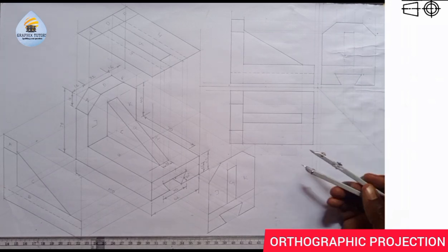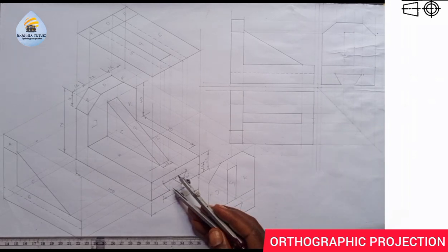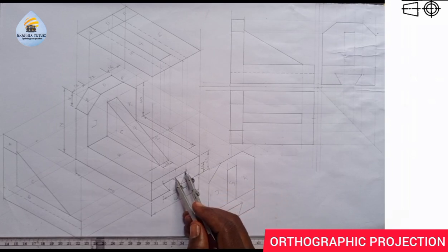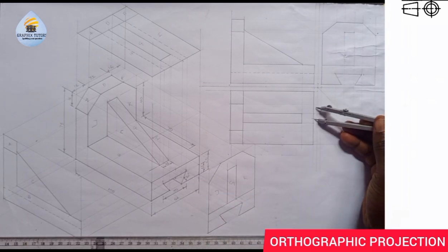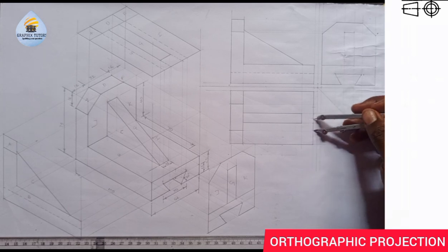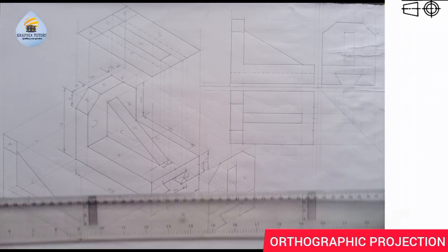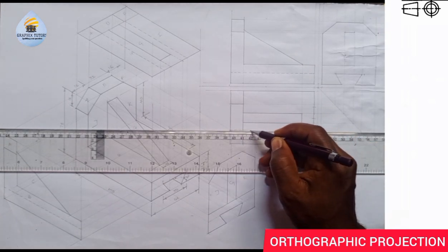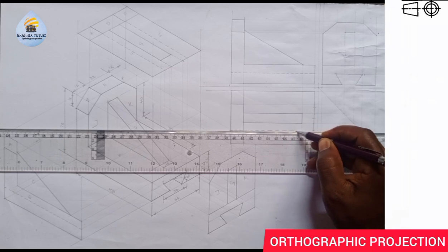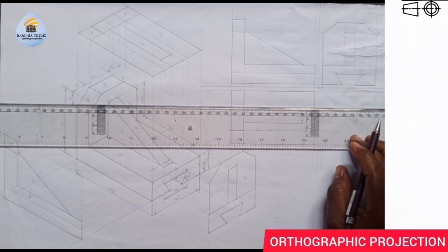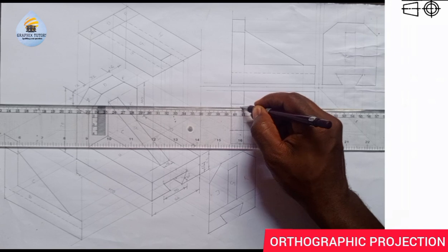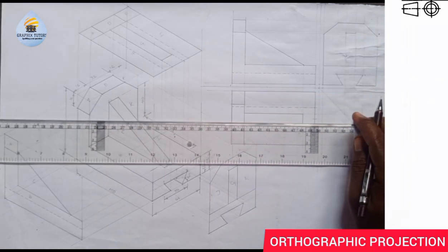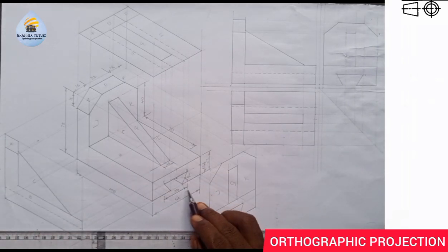The center line here. So since it is given to be 30, from the center point you measure 15 to both sides. Measure 15 with your meter rule. Place it here. Mark 15, 15. Alright? Then you draw your hidden line here. You come here also, you do the same thing too. Can you see that? That is for this. That is the length 30.